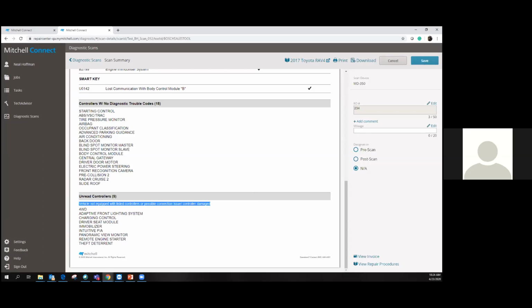I think it's more about diagnostics than pre-scan, but I'll let you answer it, right? The question is, if an airbag was manipulated with resistance, can we figure that out through the pre-scan? I think the answer to that is obvious. If there's a DTC set, then you'd know you'd have an issue, right? But if you were trying to go further than that, you would have to run a special test to troubleshoot that specific module. But yes, exactly.